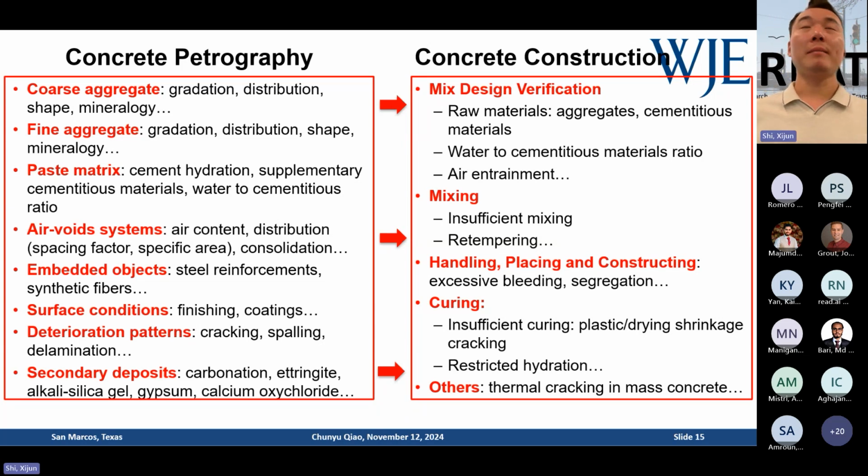So we'll evaluate the cement hydration to look at if there's any curing issues, any surface curing or internal curing issues. So we'll look at what's the composition of it. Does it contain any supplementary cementitious materials or alternative cementitious materials, like the nature of the paste? And also a major aspect for petrographers, a lot of times it's very critical for us to give an estimation of the water to cementitious material ratio, W/C or W/CM.